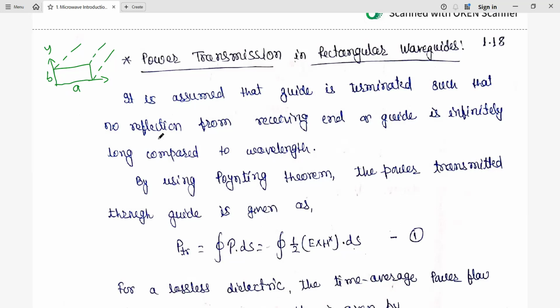Here we are considering, in general, the case when maximum power is transmitted to the load. As in the maximum power transfer theorem, the load impedance and Thevenin's impedance are equal. In case of AC, they are conjugates of each other.